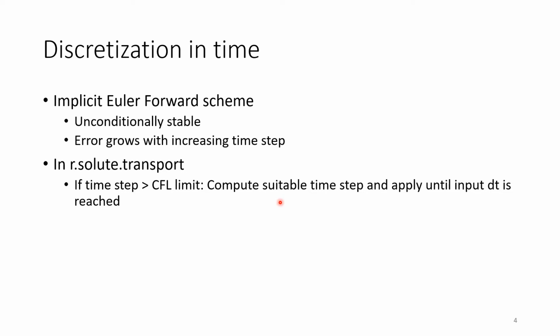And then, it is adding up time steps until your input time step is reached. And then the computation is done. Right, so here there is some internal time stepping. So you're not gaining pretty much from the implicit stepping. But of course, your criteria is stable. But it's still internally computing a time step that fulfills the CFL criteria, not for stability reasons, but for accuracy reasons.